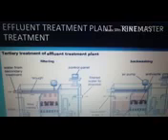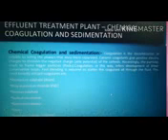And chemical coagulation in the effluent treatment plant: chemical coagulation and sedimentation. Coagulation is the destabilization of colloids by neutralizing the forces that keep them separated. Cationic coagulants give a positive electric charge to reduce the negative charge of the colloids. Accordingly, the particles collide to form larger particles, flocs. Coagulation thus interferes with the growth of small compact aggregates. Rapid mixing is required to disperse the coagulant throughout the liquid.